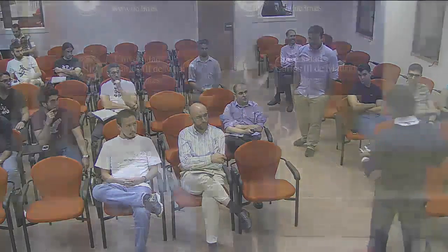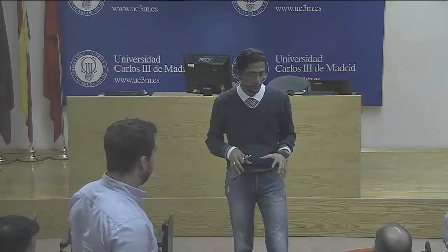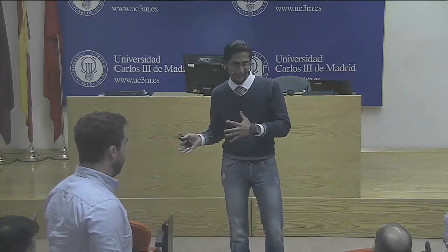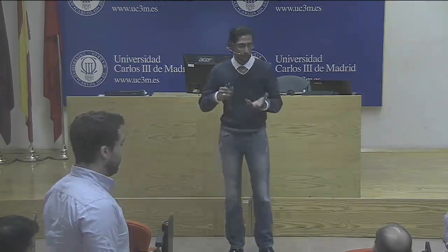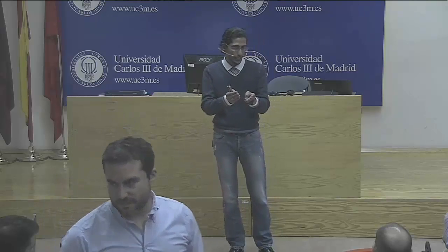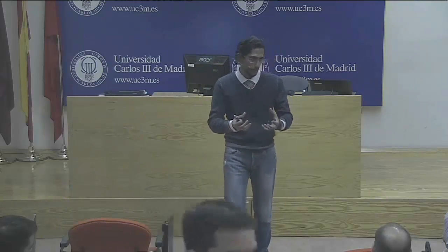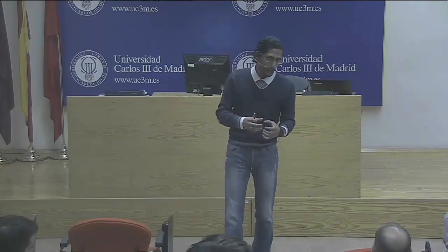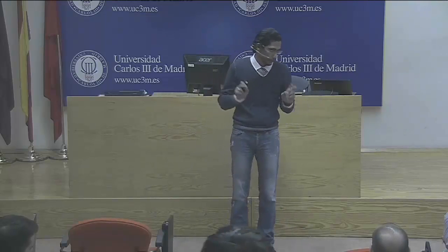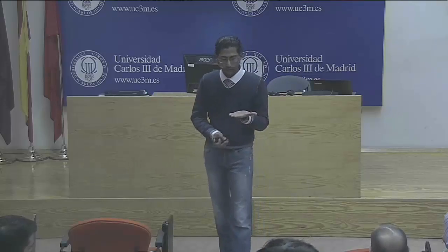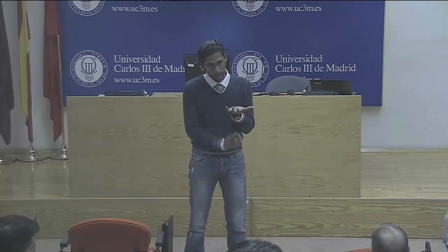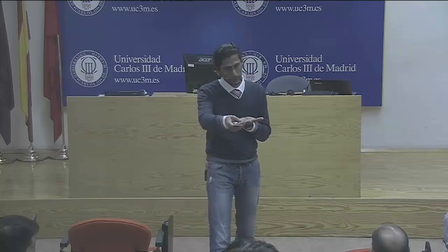How do you know the odometry of the movement of the Parrot? This is from another camera. We have a vision-based odometry. I explained it in the last presentation. We can use the gyroscope, but it's good using the visual from our drone, I mean, low cost. So we have the position from another camera, the vertical camera, and we have the frontal camera to detect the obstacles.